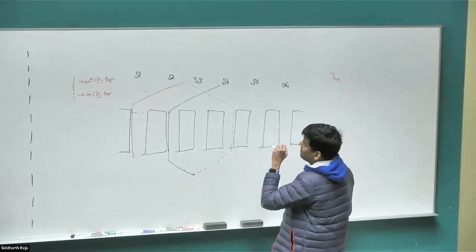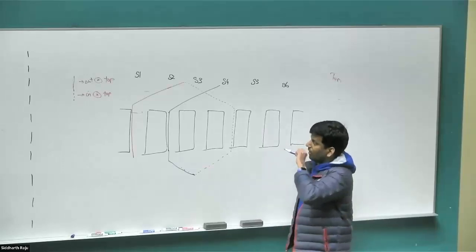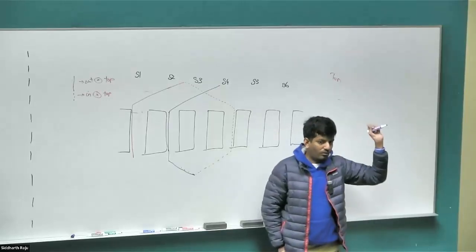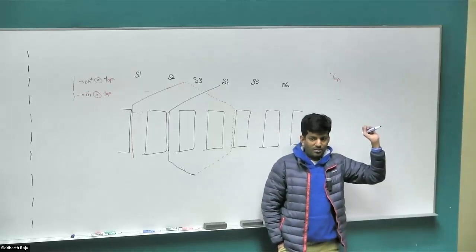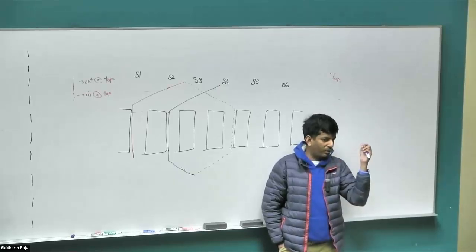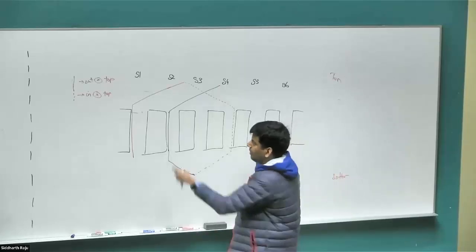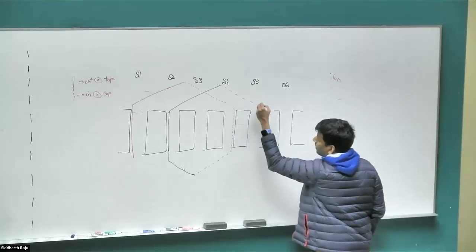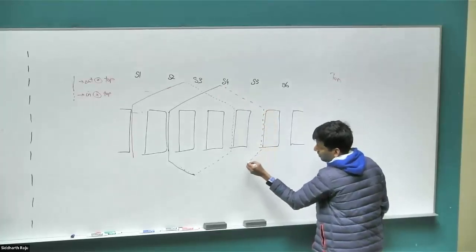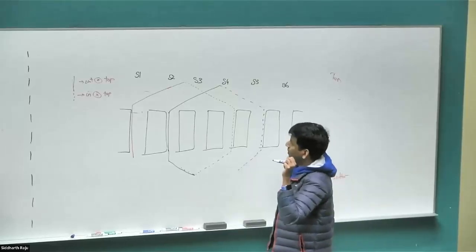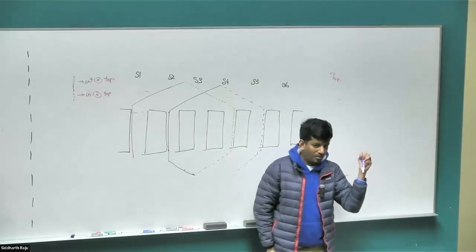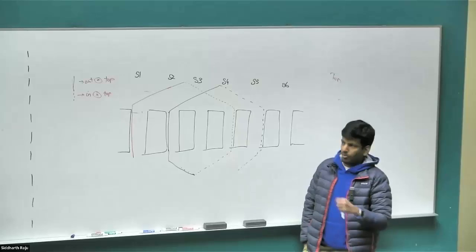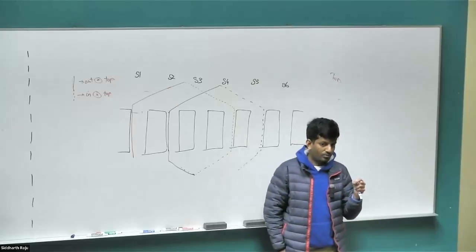It is used though. Okay, from slot 2, the conductor on the top, where is it going? On the top, it's always 180 degrees apart, right? So in case of our 6-slot machine, what is 180 degrees apart? 3 slots away. So starting from slot 2, where should it go? Slot 5, thank you. And in the bottom, from slot 5, where is it going to go? So on the top, it's 3 forward, on the bottom, it's 2 backwards. Straightforward, right? From slot 5 to 3.